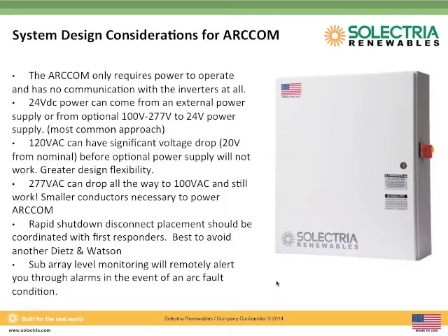And it's always just a really good idea as far as an O&M perspective. The rapid shutdown disconnect location is something else that we always have a conversation about. The code is not very clear as to where that disconnect or rapid shutdown button should be located. So what we are telling people is to have that conversation with your utility, have that conversation with the first responders, be it the firefighters, a medic, or the police, and